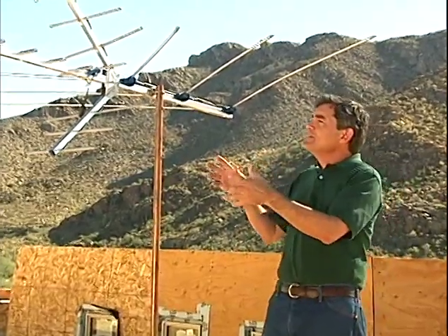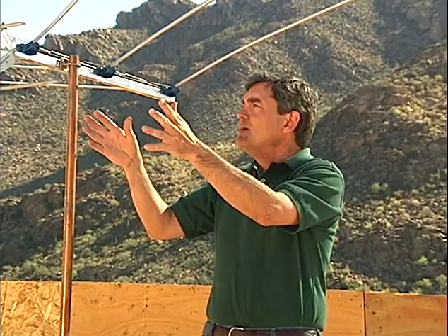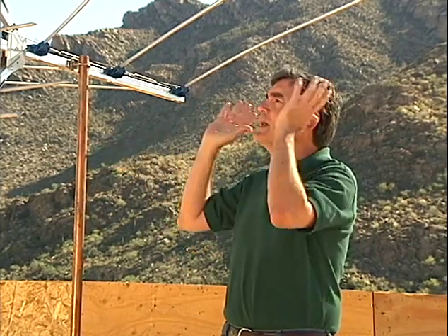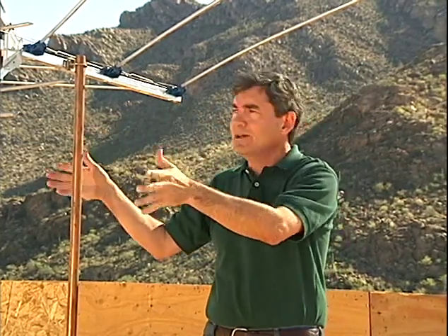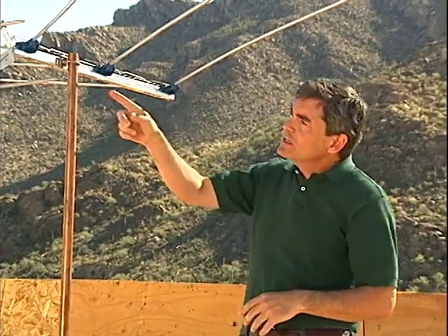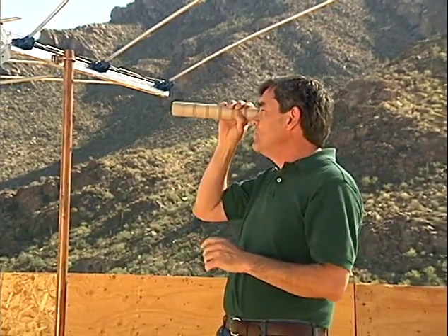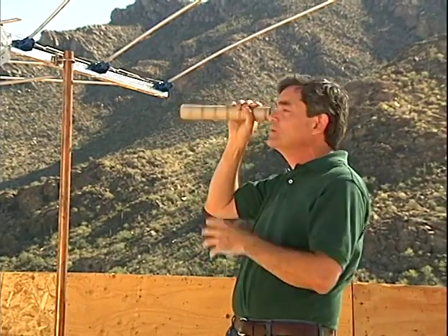Now, the other myth is that antennas somehow pull in RF signals. In fact, TV antennas no more pull in RF signals than my eyes pull in light from the sun. Antennas are in fact passive devices. They'll only receive electromagnetic signals that arrive at the antenna. If it doesn't get here, we don't pick it up. However, antennas such as this can be designed to favor signals from a particular direction, sort of like me holding up a tube to my eye to favor light from a particular direction.